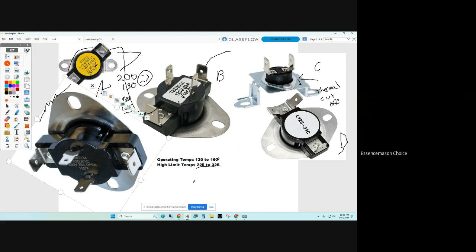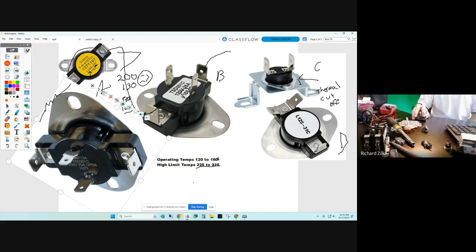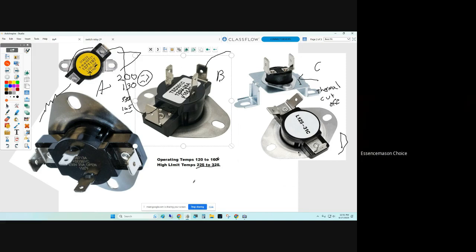Yeah. But it has 4 plugs. Yeah, it has a little bias heater on it, and this one has a bias heater. I don't want to get into that today, but that's a whole other subject. But the thermostat contact itself, in other words, hey, I have one on my truck, but I don't have a Whirlpool one. Can I use this? Well, if I know that they're both 155-degree thermostats, you can use either one. It doesn't matter. So that's an operating thermostat. These were high limits on the outside. Any questions on those? No. Operating.